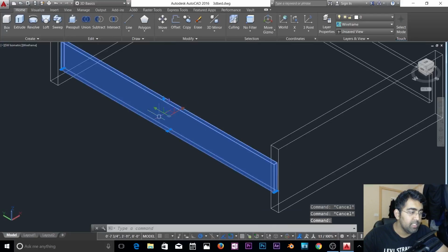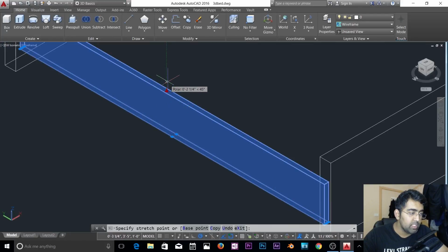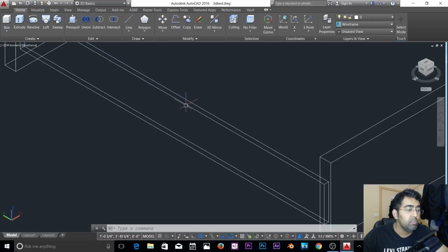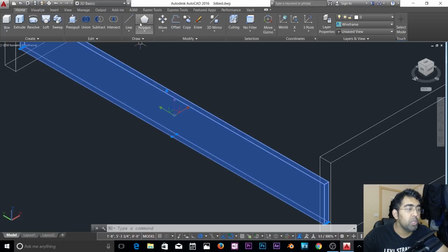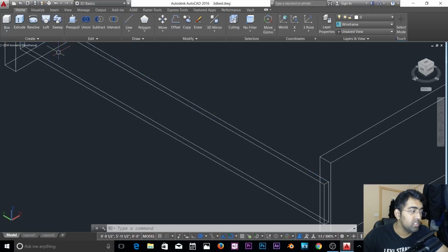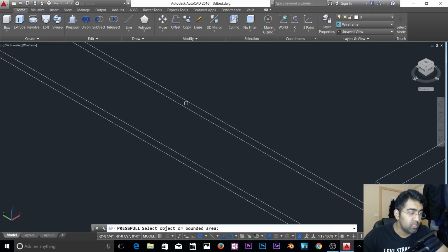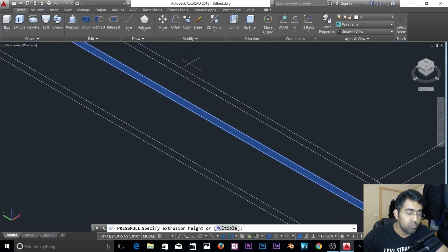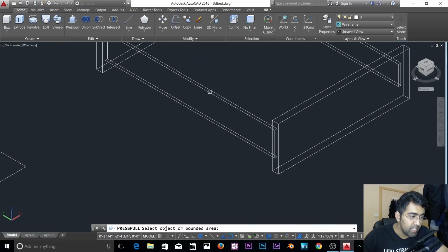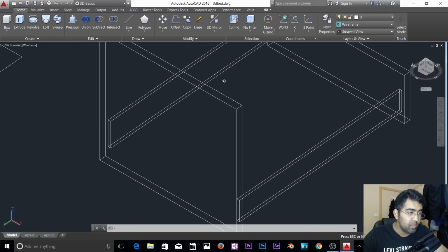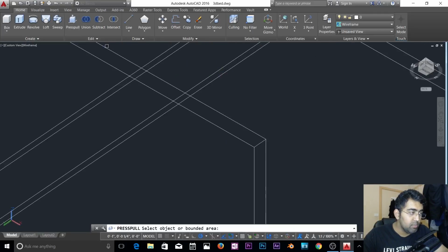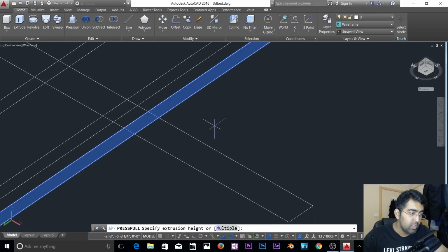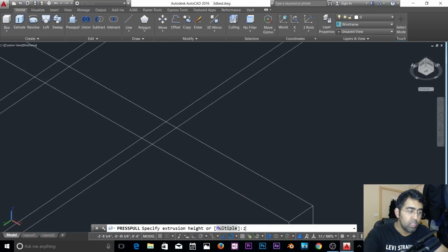So with this, I'm going to select that vertex and I'm going to click here. It doesn't work because this is a solid object. If you want to change this to surface modeling or NURBS, then you can do that with the rest of the tools. But for that, let's press pull it. So I'm going to select this part and I'm going to try pulling it 2 inch. Okay, and let's select this part. So I'm going to hold down shift key and I'm going to orbit to the bottom, right? And let's press pull this part as well. So let's bring it down 2 inch.